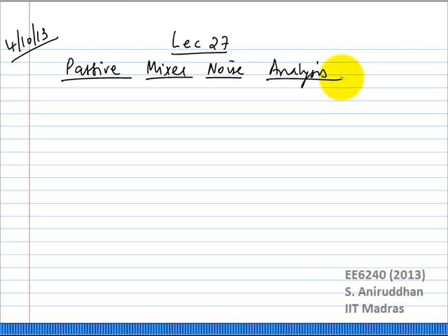The MOSFETs, okay. What else? LO may be noisy, but LO noise we'll ignore for now. The MOSFET really may be noisy, right? If you assume you have an ideal LO signal, the only source of noise here is the MOSFET, because the output is a capacitive load, or maybe if you have a current mode driving into a virtual node, that is even better. You may have the input referred noise of the amplifier, which you can analyze in a different way.